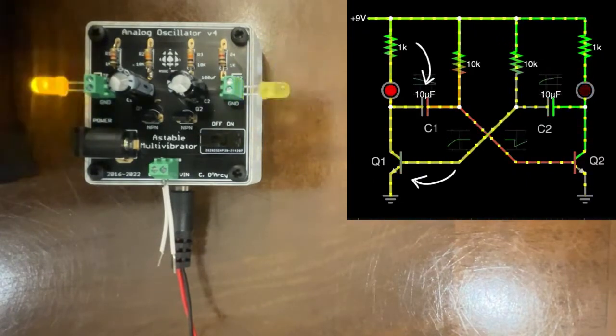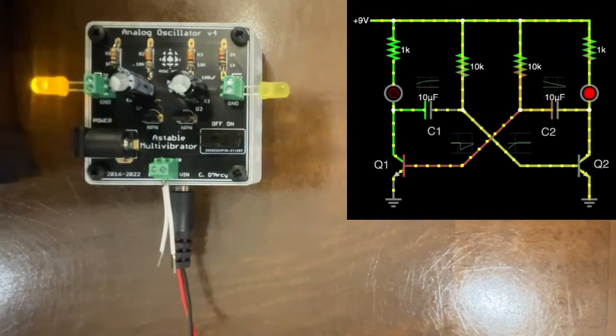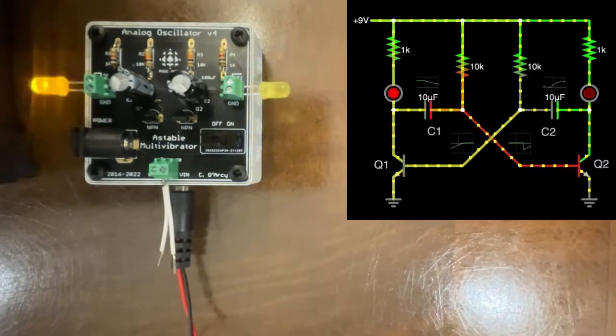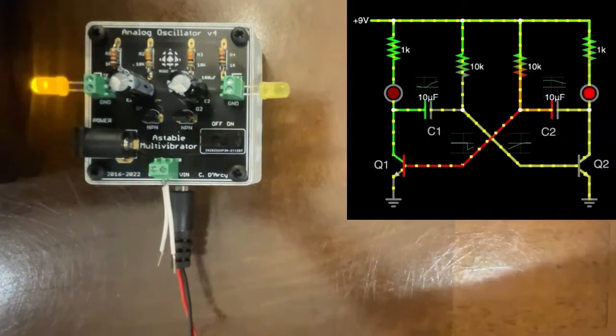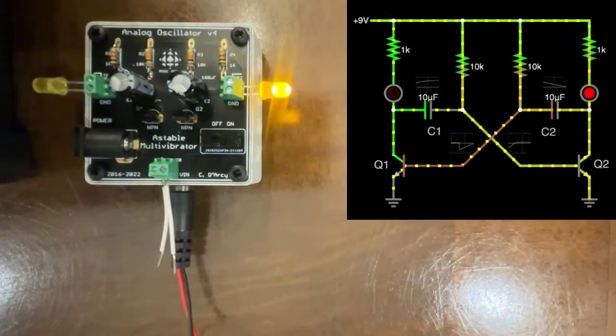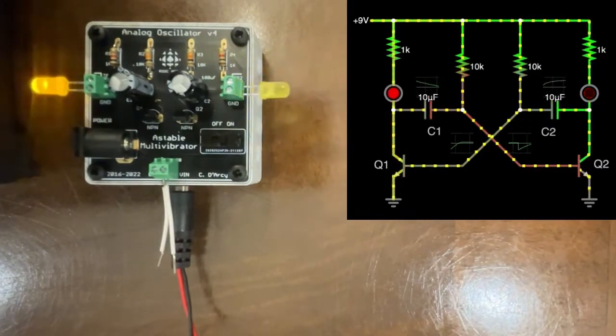This continuous cycle results in alternating on-off states for the LEDs, producing a flashing effect controlled by the timing components in this circuit. Such a continuous back and forth is ensured by the positive feedback loop so that one capacitor is able to charge at the same time when the other is discharging. Taking a look at the completed build and the Falstad animations, we can see this in action.